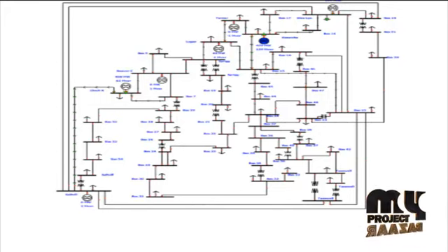The sending end and receiving end voltages are assumed to be fixed. The sending and receiving ends are connected by an equivalent reactance X. By assuming the resistance of high voltage transmission lines as 0, the receiving end is modeled as an infinite bus with a fixed angle of 0 degree. The sending end has angle delta, and V_S and V_R are the sending end and